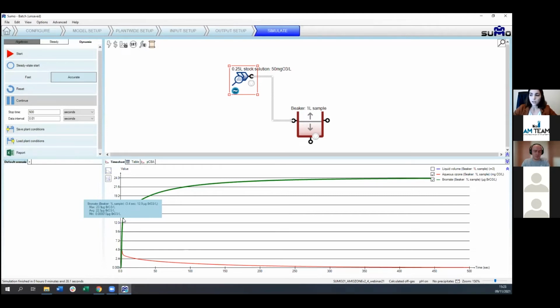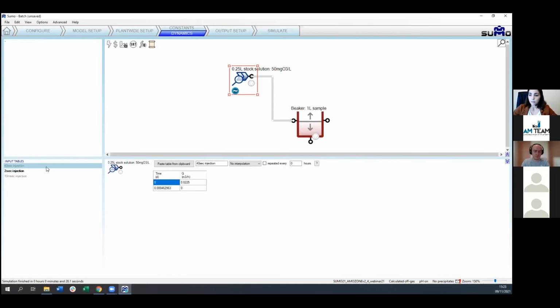In terms of bromate formation, we can see that bromate is again formed within the first few seconds, and we reach 13 micrograms per liter after 3 seconds, more or less, and ultimately at the end of the experiment we reach 24 micrograms per liter. So we have seen that within 10 milliseconds we form 28 micrograms per liter. Now within 2 seconds of injection we are producing less bromate, 24 micrograms per liter. Now let's see, last example, what happens if we inject ozone within 40 seconds.